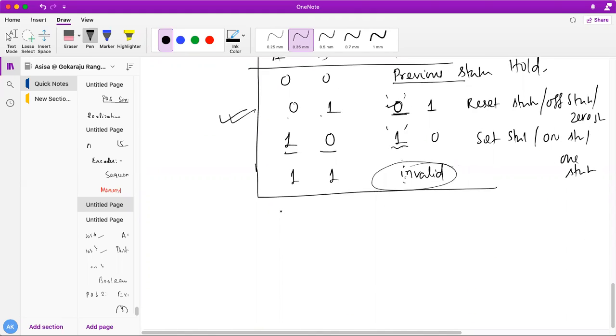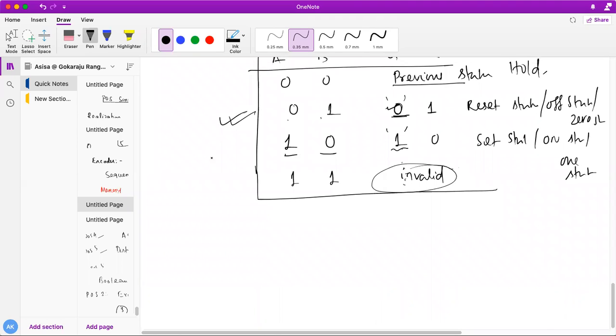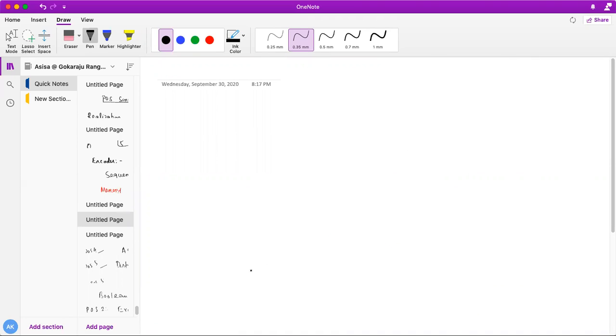So it's very simple. Now we'll go to the next part. Any doubt on this, students? Very simple, whatever I have explained, nothing else. So next we'll go to the flip-flop. What is the difference between a latch and a flip-flop? We have just discussed the latch. What is the difference between a latch and a flip-flop? A latch is nothing else; it is controlled with the help of the input. As long as the input doesn't change, my output won't change.